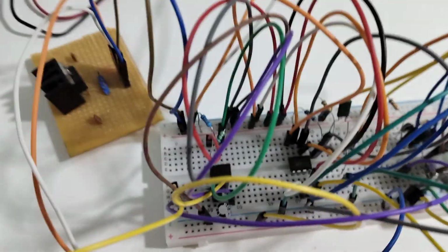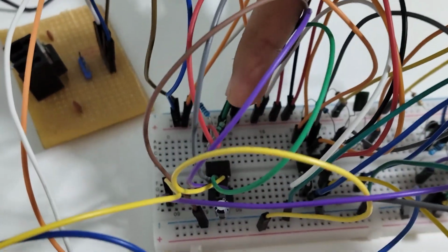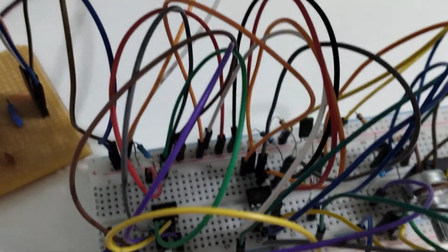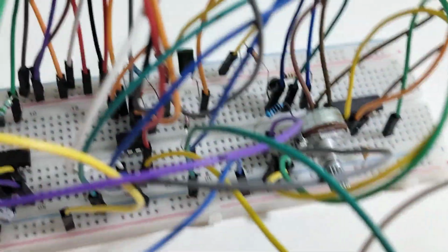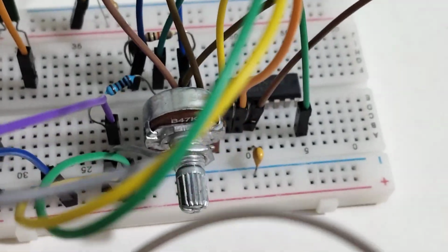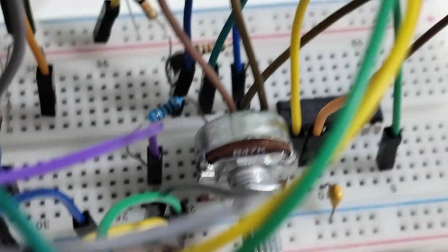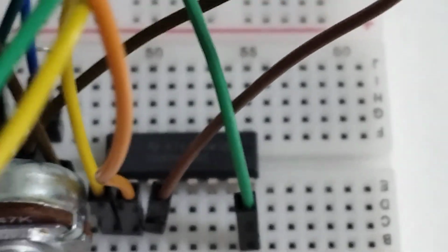After that, it goes on here to this stage, and you don't need to worry about this IC here. This is another 555, but that was for another thing, so it's not really a part of it. Only this IC onwards is the actual circuit, so ignore this part. So it goes on here, as I showed, to the series resistor and the pot to vary the firing angle. It's a 47k pot. And after that we give it here, this is the inverter, the CD4049.